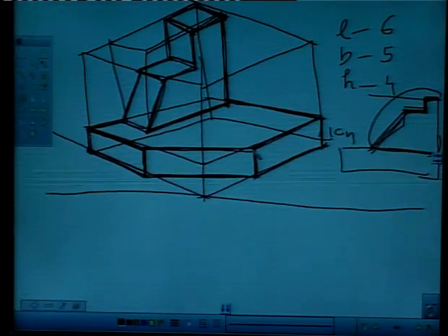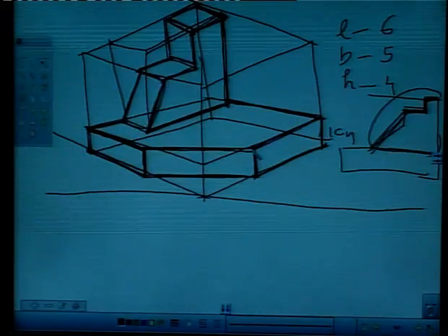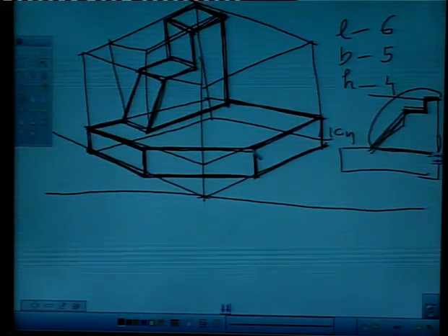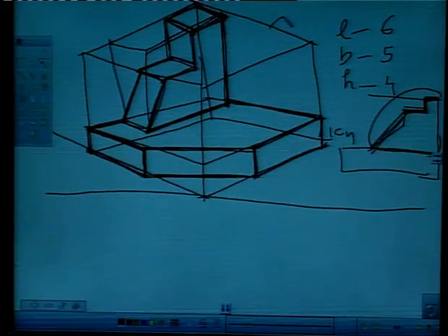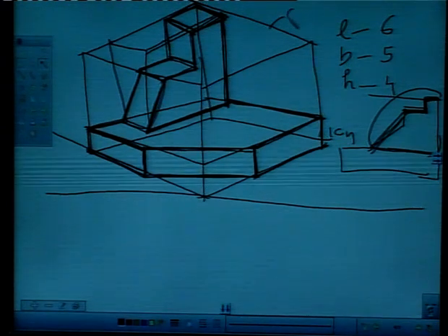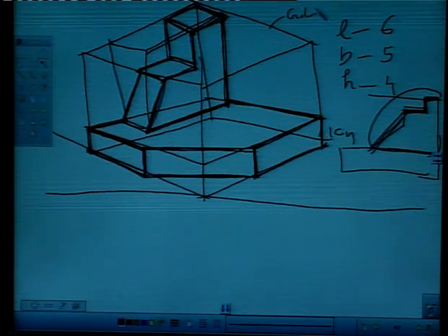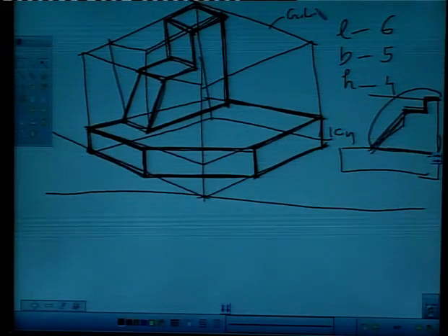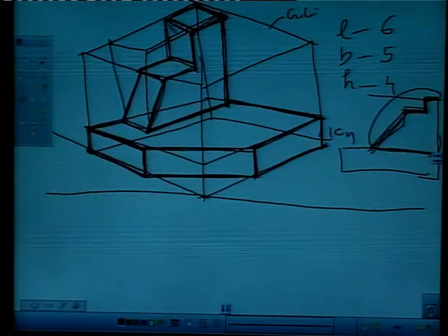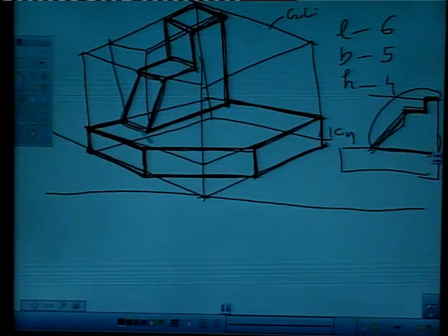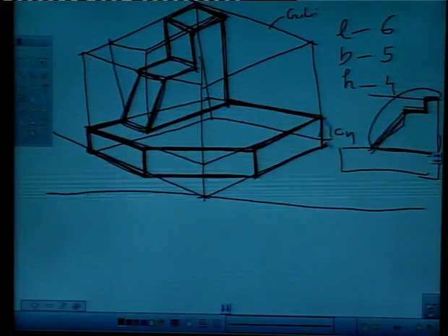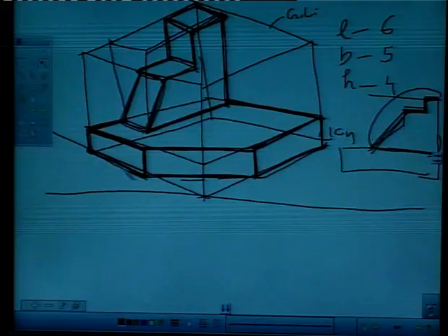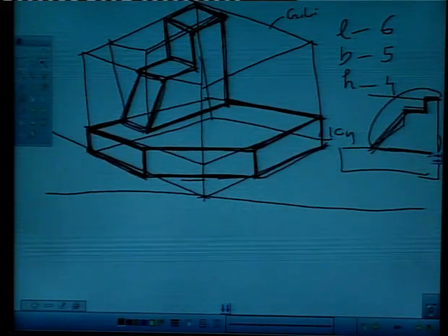Right? This gives us the isometric projection of a given orthographic projection. We need not erase these lines, right? They should be guidelines only. I am writing these guidelines, the lightest lines, just for your knowledge. You need not erase these lines, just darken your final edge lines. Right? I hope it is clear to you.